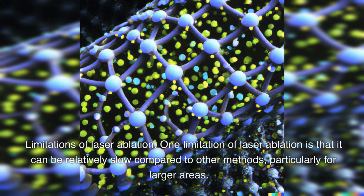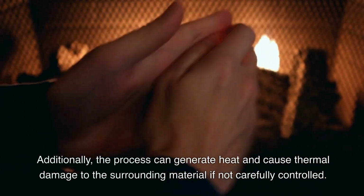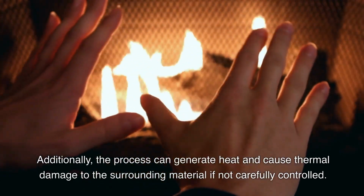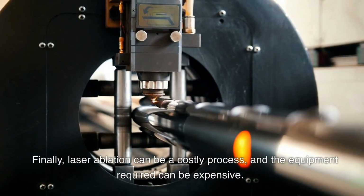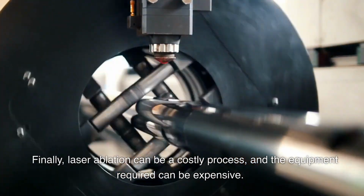Limitations of laser ablation. One limitation of laser ablation is that it can be relatively slow compared to other methods, particularly for larger areas. Additionally, the process can generate heat and cause thermal damage to the surrounding material if not carefully controlled. Finally, laser ablation can be a costly process, and the equipment required can be expensive.